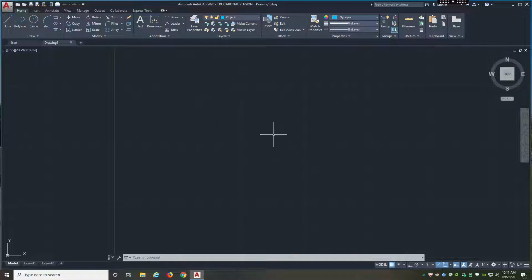So essentially, let's just start drawing the object line here. We're going to draw that front view, right, which is the most descriptive view. So let's see, turn my ortho on, 5 inches.